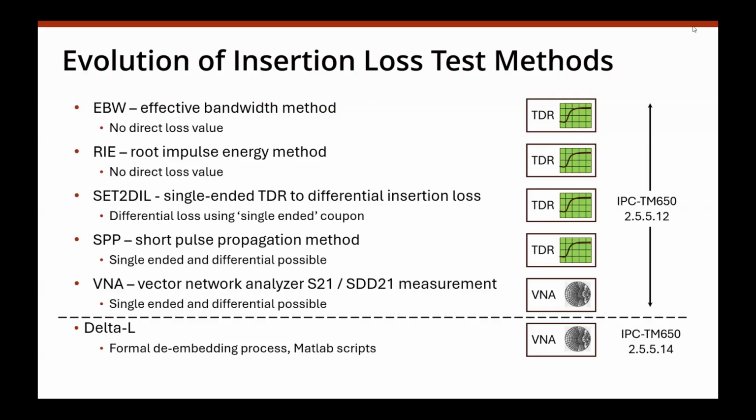But under the assumption that it's more the DF and the copper roughness and the processing that affects that, and that would be the same in a full batch of PCBs, you can get away with doing sample testing of a few coupons on a lot, and you get a pretty good understanding of what the actual insertion loss will be.